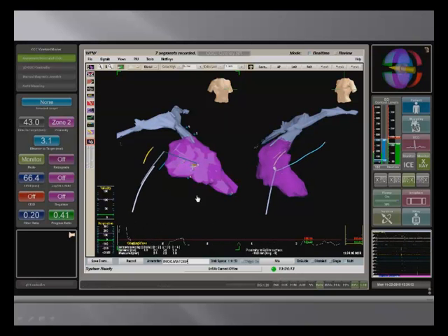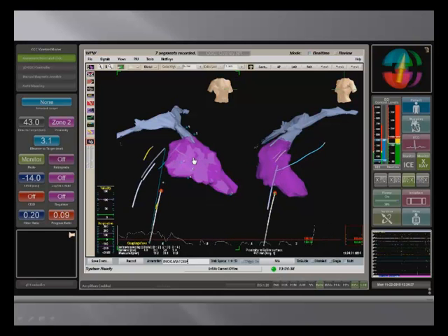Can you define the trajectory? Yes. Once you have a map, you can define any trajectory. You can tell it, I want you to go here, here, here, and it'll go to every point. You can create a circle and tell it, that was what I was trying to show earlier in the animal model, create a circle and tell it to go clockwise, counterclockwise, any degree on that circle that you want to go to. You have to have a full angiographic map. Either an angiographic map, which you digitize, or you make all the movements first and create all of these spots, and then the machine will integrate where you've been into a 3D shell, and then you move within the coordinates of the shell.